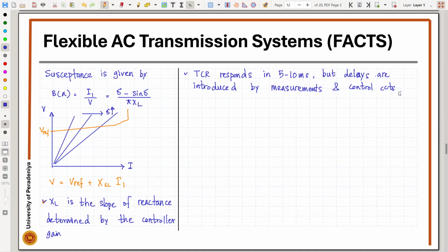But in most of the cases, as we discussed in the initial section, we can see voltage drops in the night time. That happens because the loads will be absorbing the reactive power provided by the network, and along the line there is a voltage drop. So if we want to increase the voltage, then we need to provide reactive power. So we need to have some sort of circuit to provide the reactive power to the network as well. That means we have to connect capacitors and provide the reactive power to the network.